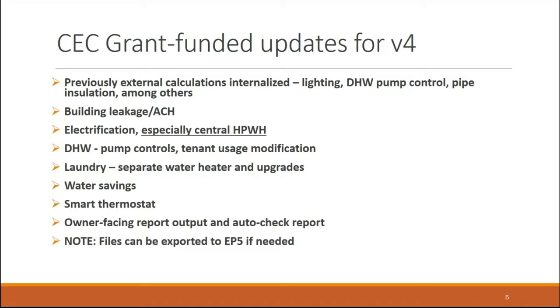I'd like to note that EPL files can be exported to Energy Pro 5 Full if you need to. So part of the reason Energy Pro Lite is pared down, easier to use, is because we're making some assumptions in the tool. I won't get too much into it because there are workarounds, but if you cannot accurately model a building using this tool, you can export it to Energy Pro 5 Full.